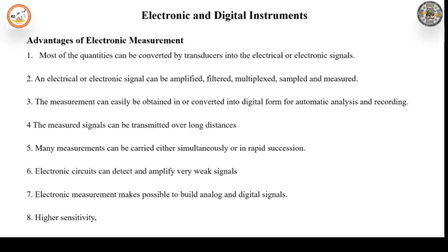In olden days, vacuum tubes were in use, and the voltmeters were called vacuum tube voltmeters. But nowadays, transistors and semiconductor diodes are used in the electronic voltmeters. A voltmeter in which transistor is used is called transistor voltmeter. The field effect transistors are also used at the input side, and such voltmeters are called FETVM.